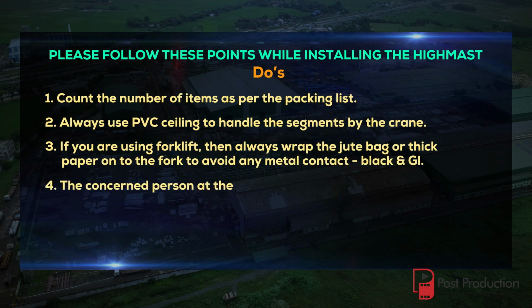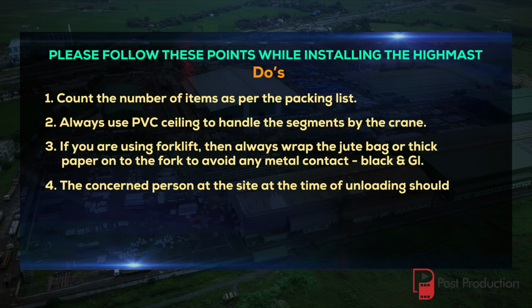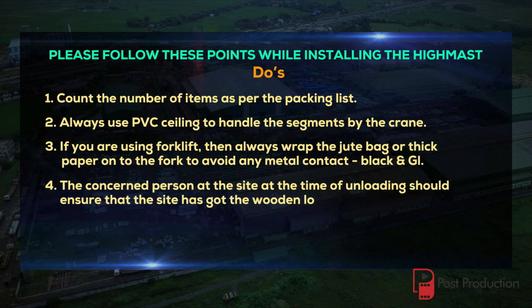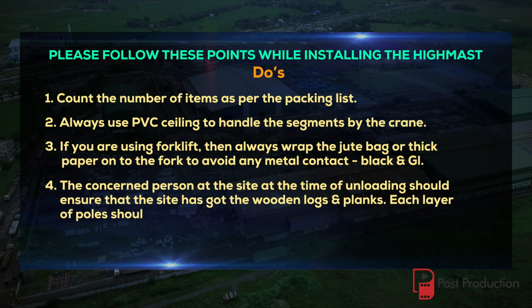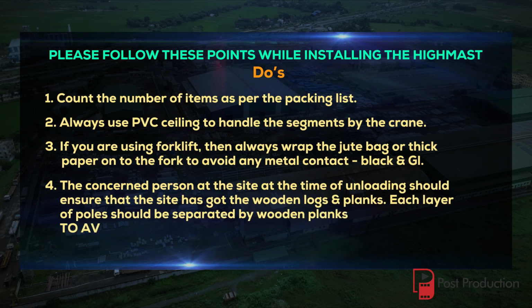The concerned person at the site at the time of unloading should ensure that the site has got the wooden logs and planks. Each layer of poles should be separated by wooden planks to avoid white rust.